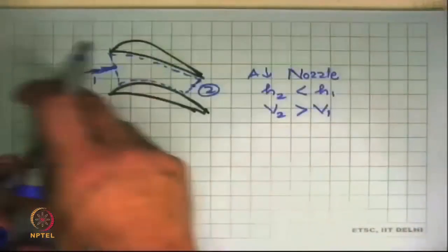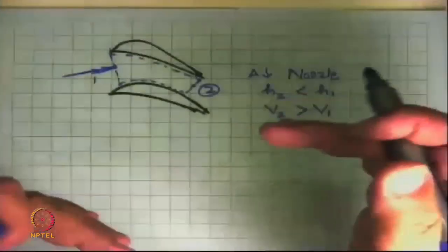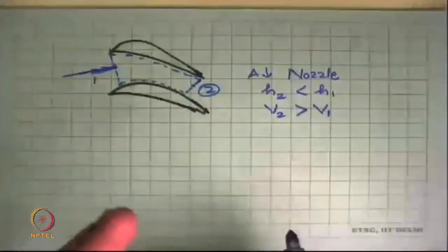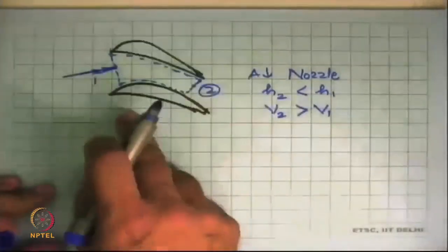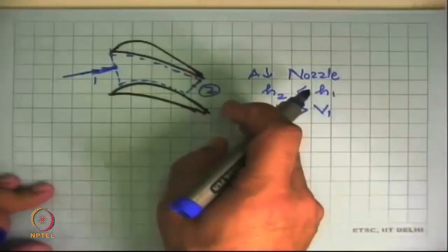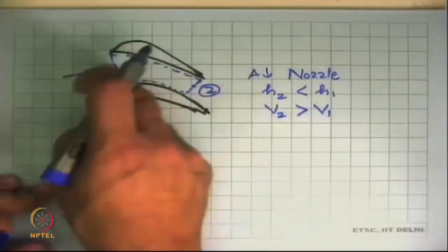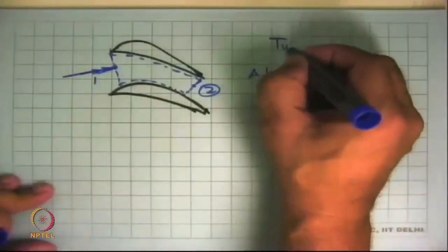So that's what one does in turbines, where we have high pressures, say steam or gas, we accelerate it, and then we pass it over a rotating set of blades, which imparts momentum to it, and that's what causes the power output from a turbine. The opposite is done when we look at compressors. So you have the same shape, but now you are putting in from this side and you decelerate the fluid. So this is a realization on turbo machines.